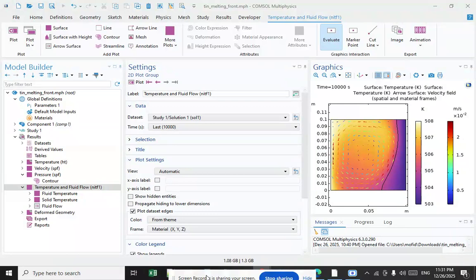In contrast to viscosity, thermal expansion and heat capacity of amorphous materials show a relatively sudden change at the glass transition temperature, which enables accurate detection using differential scanning calorimetry measurements. Lev Landau gave a phenomenological theory of second-order phase transitions.